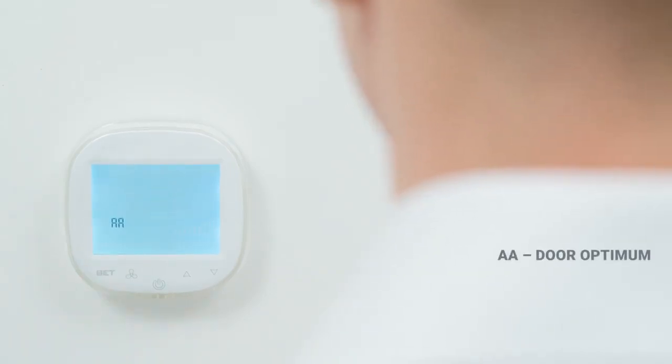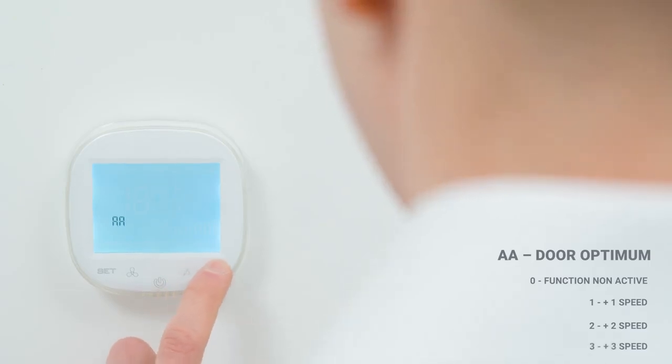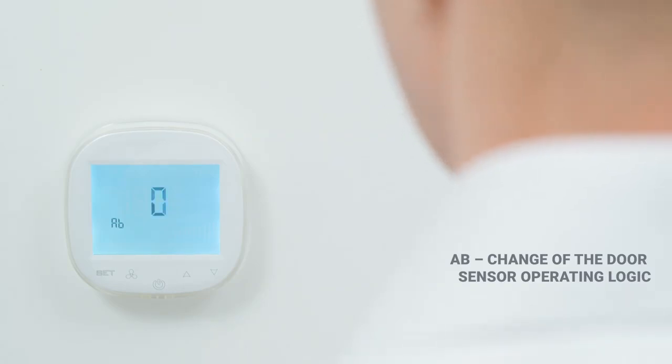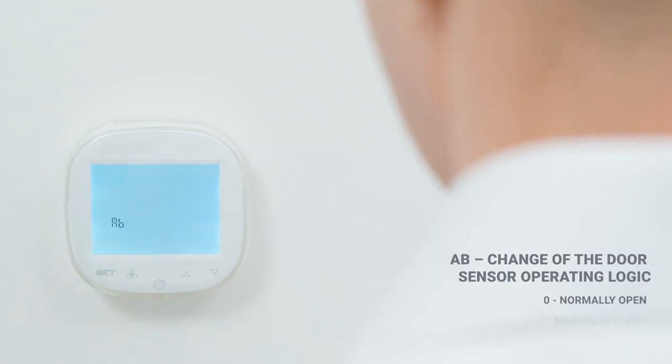Function AA: this is the door optimum function. This function is used for wing operation with a door sensor. When the door is open, the speed is increased by 1, 2 or 3 gears. Function AB: change the door sensor work logic. 0 means normally open, 1 means normally closed.